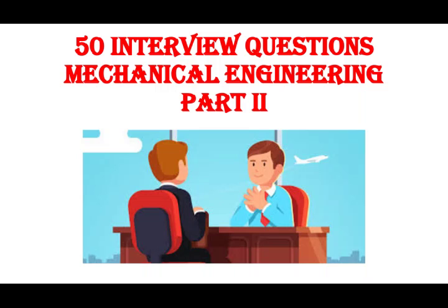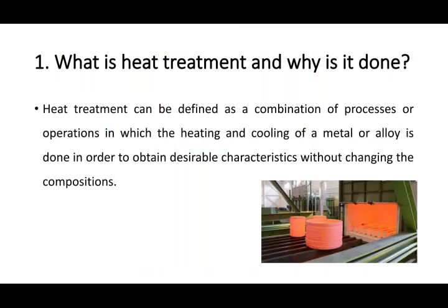Today in this video we are going to discuss 50 technical interview questions which are generally asked in the interview of mechanical engineering. So the very first question: what is heat treatment and why is it done? Heat treatment is a combination of heating and cooling processes, and it is basically done to obtain desirable characteristics. Heat treatment can be defined as a combination of processes or operations in which the heating and cooling of a metal or alloy is done in order to obtain desirable characteristics without changing the composition.